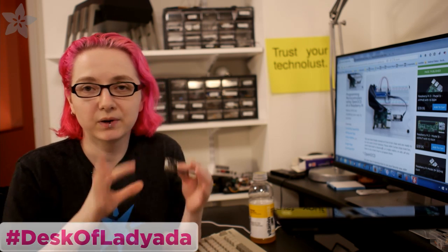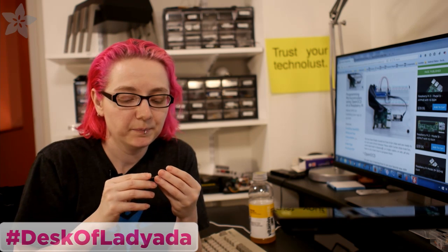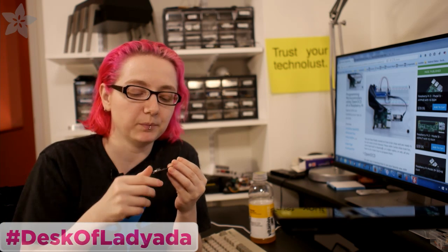I have these in the Feathers, and I'm making a version of the M0 called the Metro M0, so this is a prototype. I'm learning a lot about these chips, and one of the things I've been learning is how to program them. If you want to do development, you can usually get the compiler for free. You use the ARM EABI compiler, compile your code for the Cortex M0 with whatever special registers you need for that chip. But then you have to get the code into the chip.